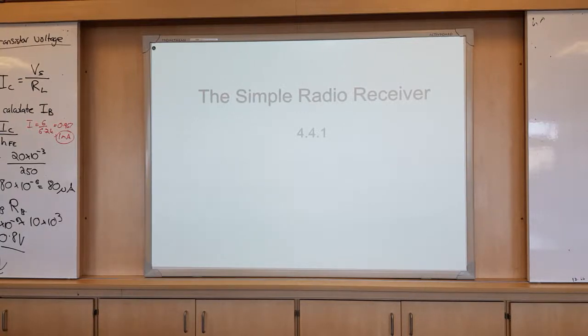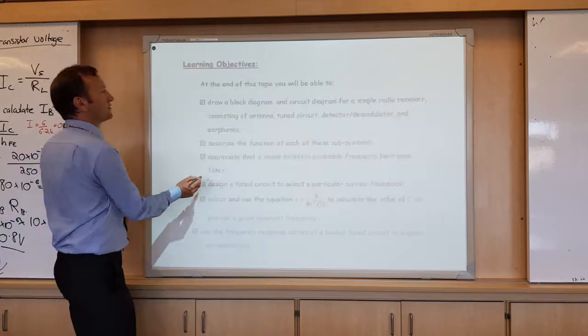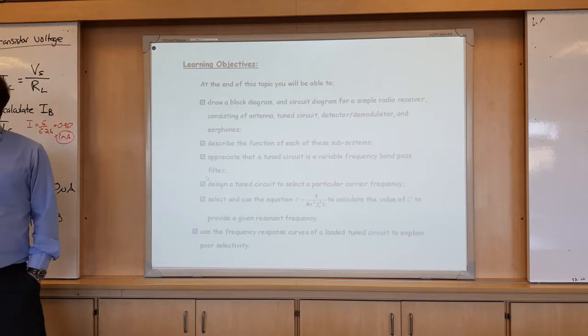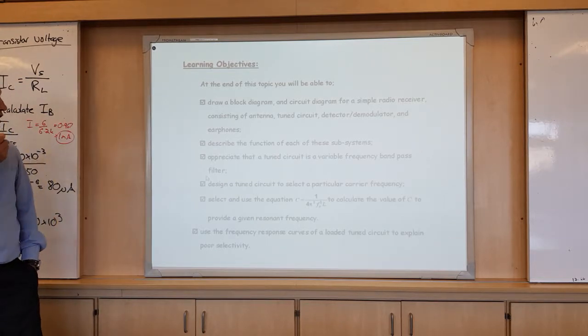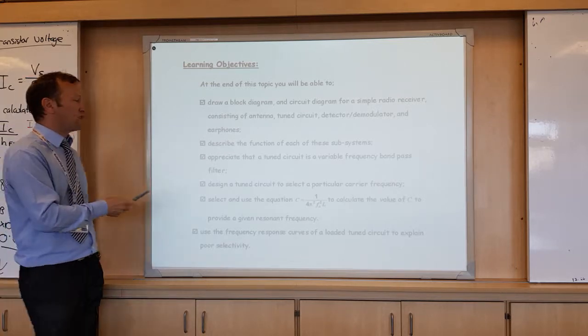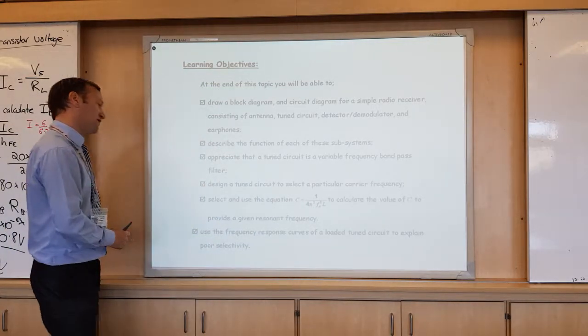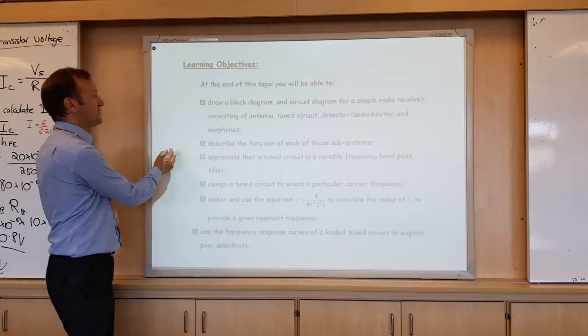Okay, simple radio receiver. You need to know the block diagram and the function of each block. You need to be able to use that formula to provide capacitor values.